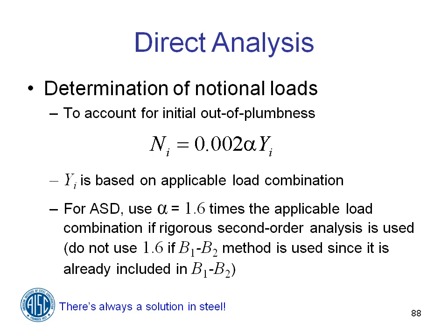Okay? But if you're calculating drift in terms of getting second order forces and moments and all, yes, you do that at the 1.6 times the ASD load combinations. Okay. Now I want to look at one last question, Lou. Yep. Sorry. Just one more.